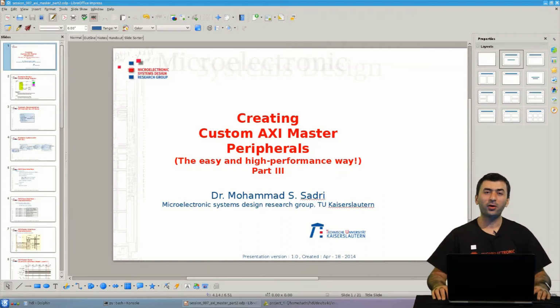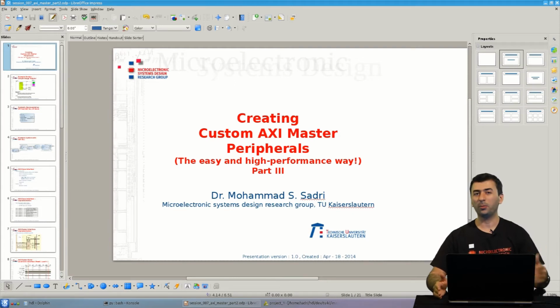Okay, now we reach part 3 of session 7, which was called creating custom AXI Master Peripherals. This is a kind of practical session in which I do simulation on my AXI image rotator IP, and through simulation I want to make sure that my image rotator controller, the module that I talked about in the previous session, is correctly working. And then we go ahead in the next session with a practical implementation on the Z board.